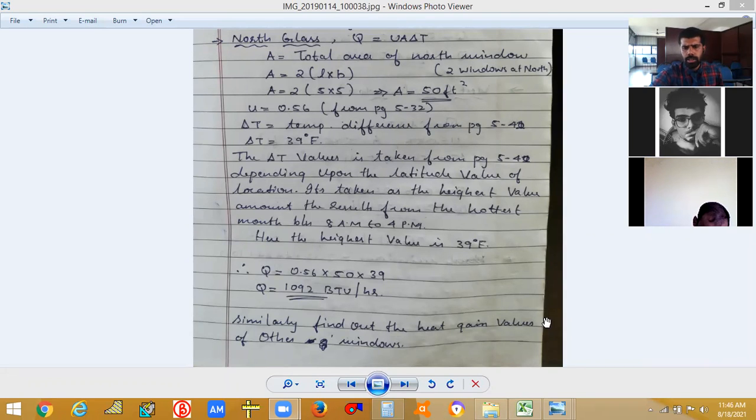Yes, Kirti, you got the correct answer. It's fine. It's correct. East glass is 4424 and west glass is 2212 BTU per hour. What about others? Are you getting the same answer? Now what you have to do is find the total heat gain through windows. Add all those values: 2212, 4424, 1092.